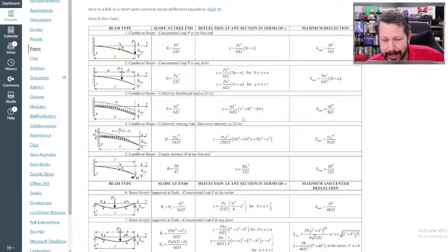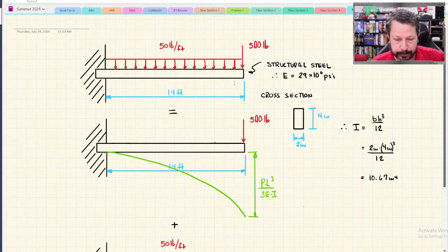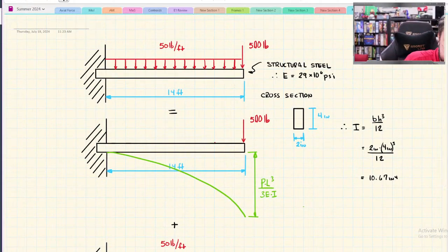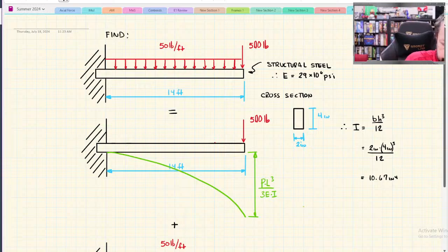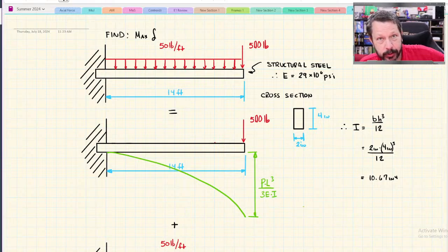Since we're doing it by hand, we're going to be a little more manual, and I'm going to say that our goal was to find the total maximum deflection. Maybe we'll write that down. So what we're trying to do is find max delta. And we know that maximum delta is at x equals 14 feet. This time I'm measuring from the wall.